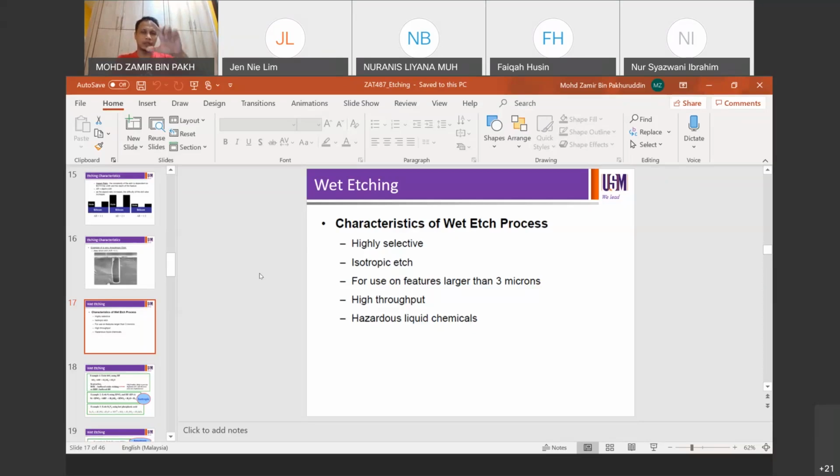It's like nano needles. Width is about 50 to 100 nm, and the height is about 400 nm up to 1 micron. It can even go up to 2 microns or a couple of microns. So the width is only 50 to 100 nm, and in that case, we still use wet etch to do the job.